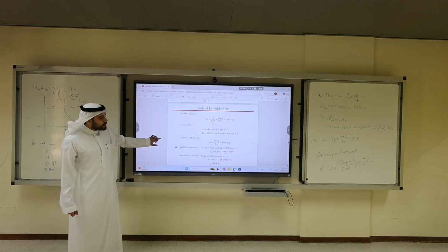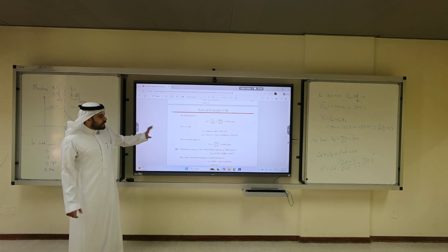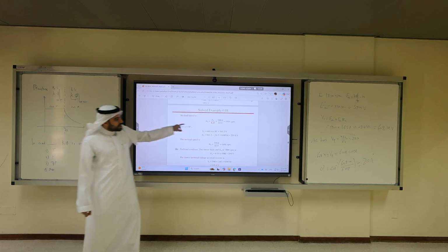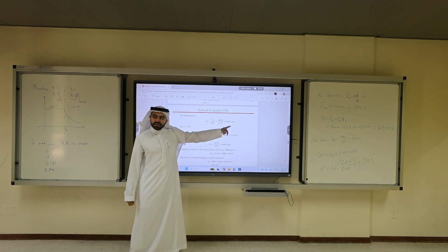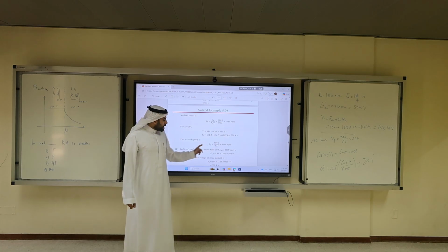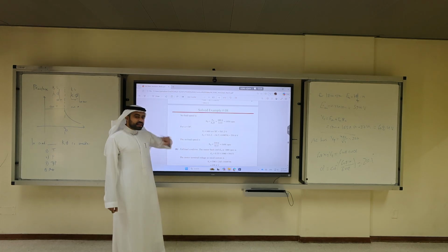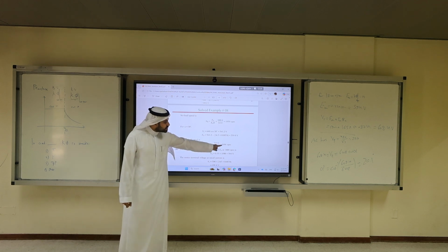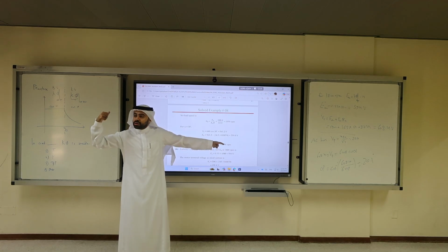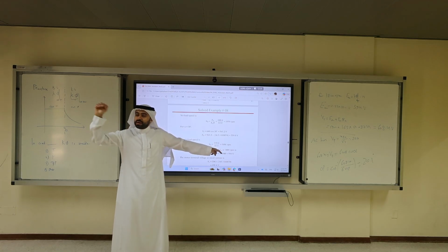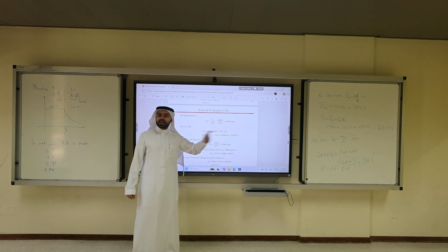So both speeds, well, here's the trick. At 0 degrees, the speed is 1959. If you change alpha, the no-load speed at a different firing angle is 1696. But now you connect a load and you adjust the alpha to be faster than the no-load at alpha 30.